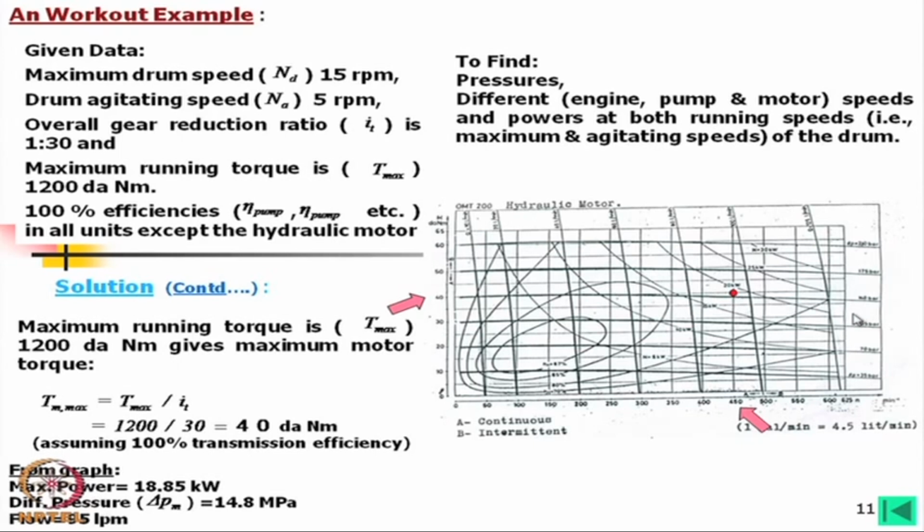If you look at this line, from low speed to high speed, it bends slightly; these are iso-pressure lines. So here we consider that this is the pressure. This is not the output pressure, it is called a differential pressure. In a motor, with oil in and oil out, when the oil goes out there is also some pressure, because there is a filter and other components.